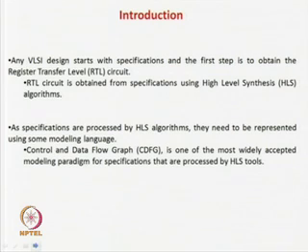Today we will see the standard ways of debugging, similar to the case of C: you run your Verilog code with different test benches, that is, inputs, and see whether it operates correctly or not. In the second module of the course, we will see formal verification methods, in which you need not apply any inputs, but can formally or mathematically verify that your design matches the specification. But there are also other steps we will see today, like optimization steps. We should not call these errors, but you can do lots of optimization.